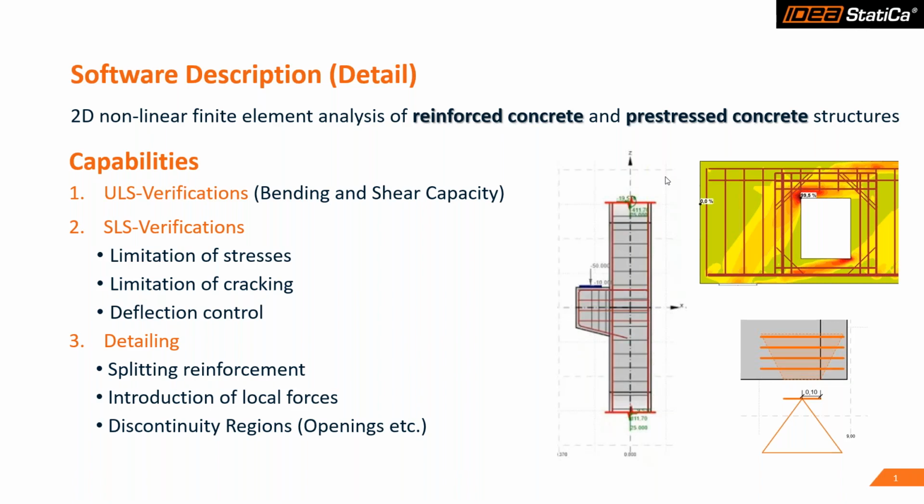What is very important about this program is that we can conduct detailing. That's why we have the name, Detail, which means that we can investigate introduction of local forces, for example, point forces, and we can calculate the necessary splitting reinforcement. And also very important is that we can investigate discontinuity regions. For example, if you have difficult geometries or if you have openings, with beam elements or with a linear analysis, it's almost impossible.